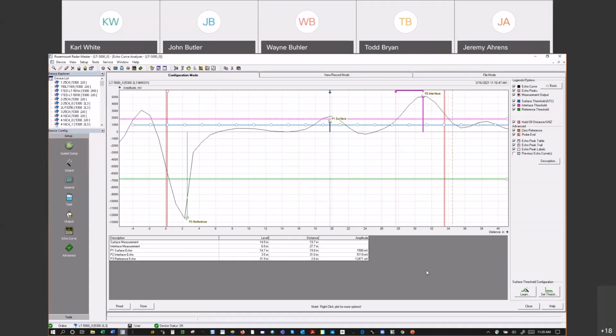One thing to note on that, so keep in mind, if you have a radar in a chamber and you have an MLI built in, like a combo 2 dual chamber, the magnetic level indicator has a float that works off density. So it's calibrated to a specific density. And that's how that float tracks.